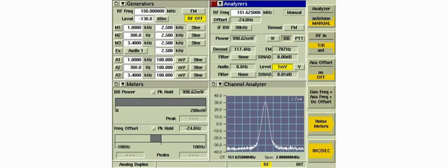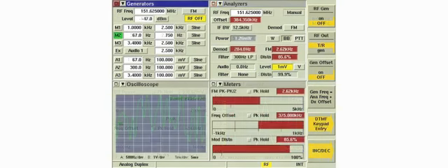Determining if a measurement is exceeding a value or if it is between an upper limit and a lower limit can be accomplished efficiently through the use of the limits function. The use of limits is particularly useful for performing a quick check of a radio's functions. In this example, limits are set up for a number of different parametric measurements of the radio.